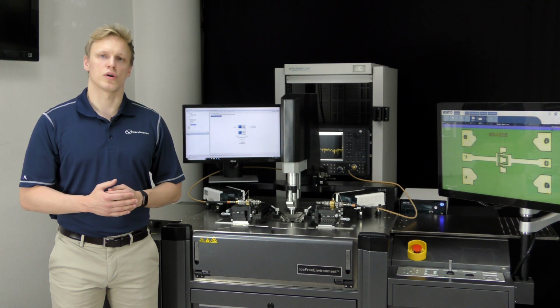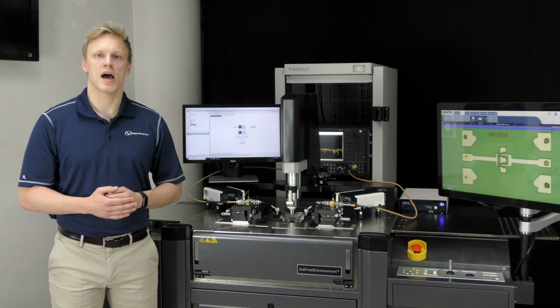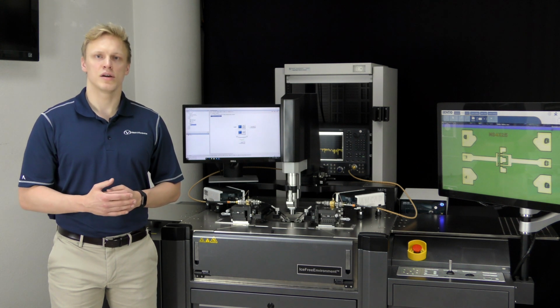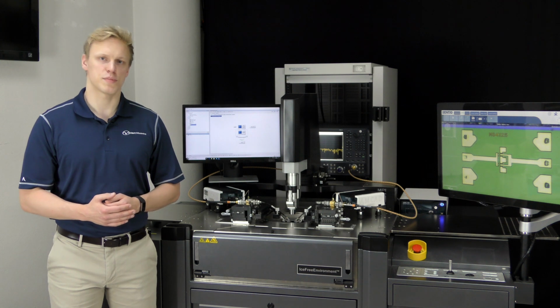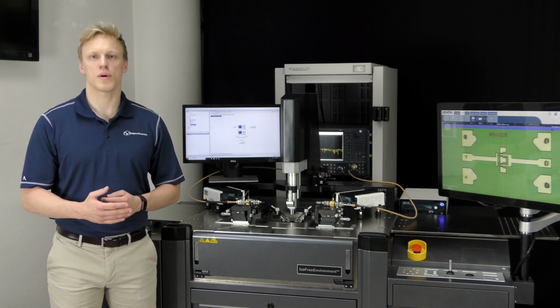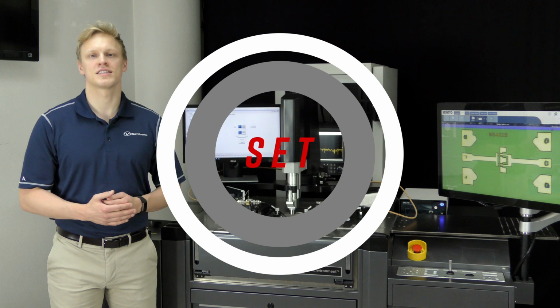Let us see how this works. First, we will take a quick DC IV measurement and then see how constant bias results in current droop. Second, we will repeat the measurement with pulse bias and show the same curves without the droop. Third, we will explore synchronized pulsed S-parameter measurements under pulse bias conditions. Ready, set, go!